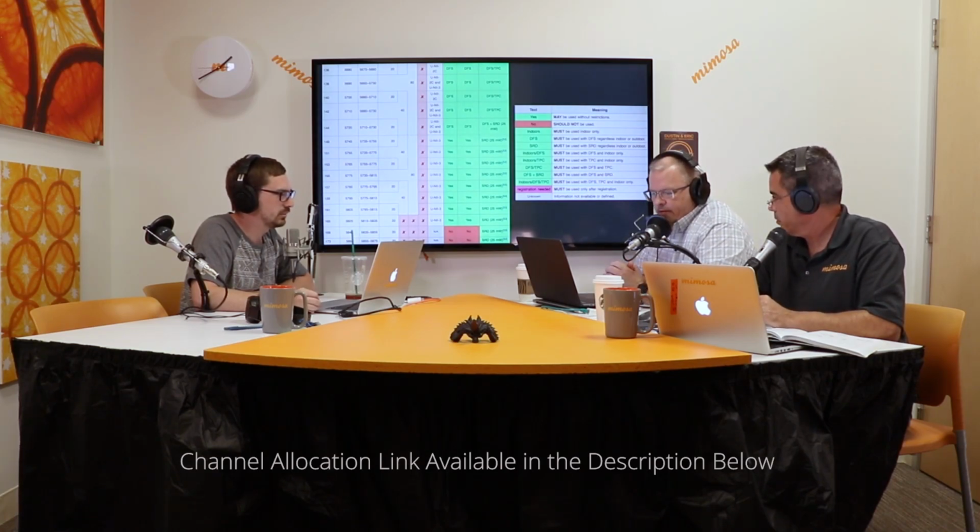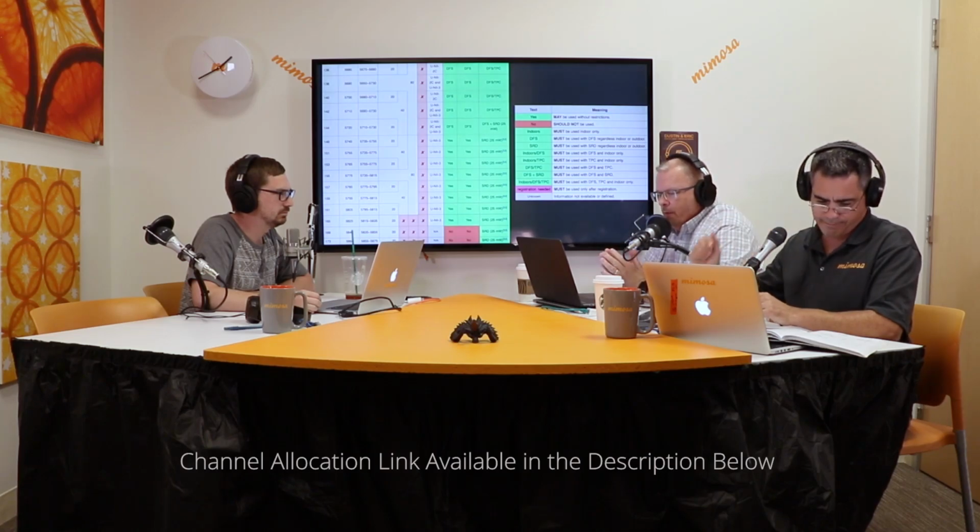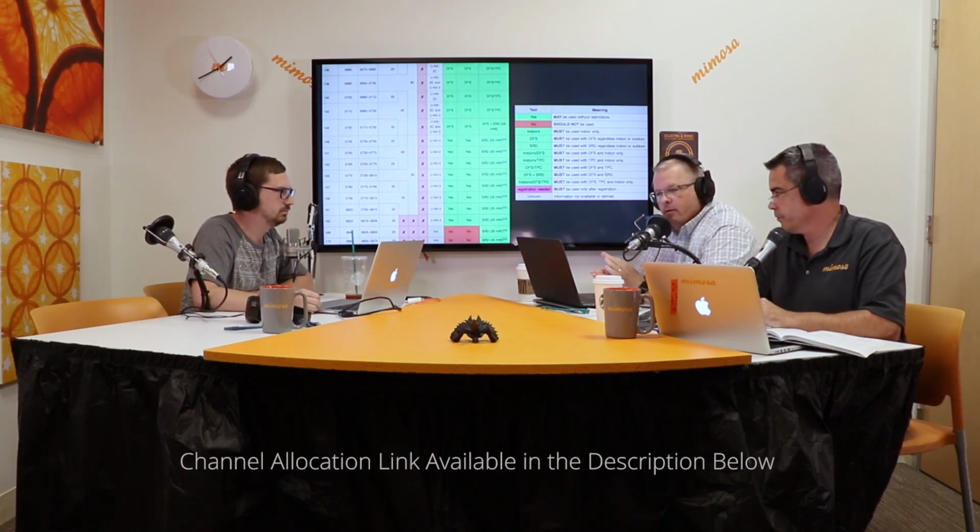Yeah, I think the one thing I would say is we see a lot of customers that may have unreasonable expectations about DFS. If you always remember that you're the secondary operator in that spectrum, and that you, by law, have to vacate that channel within 10 seconds of a radar hit, and you build that expectation into using that frequency, then I think everything will be okay.